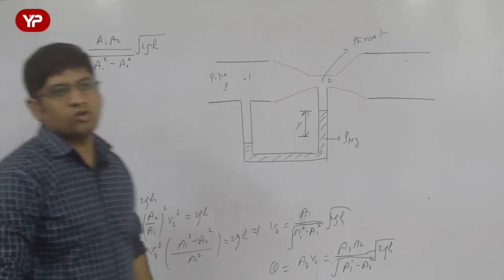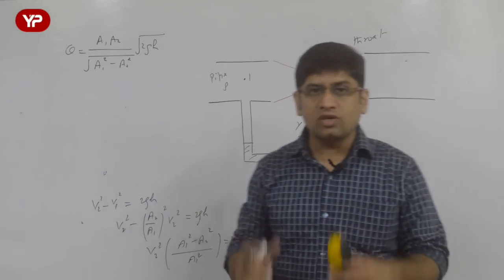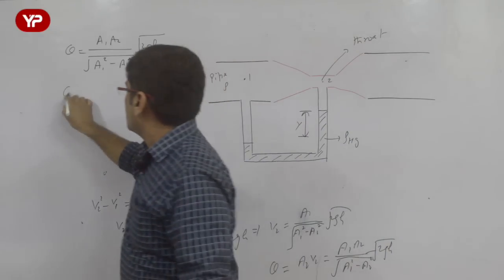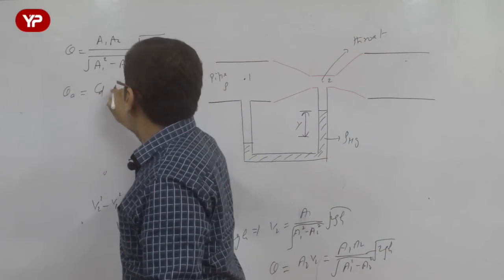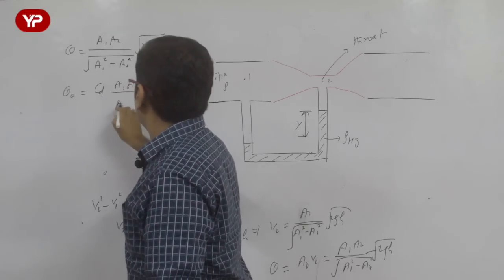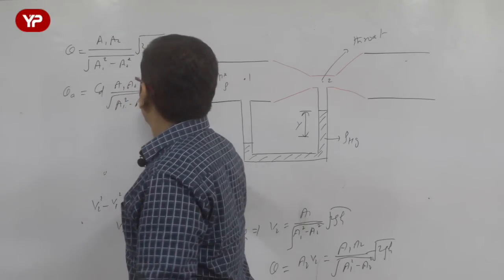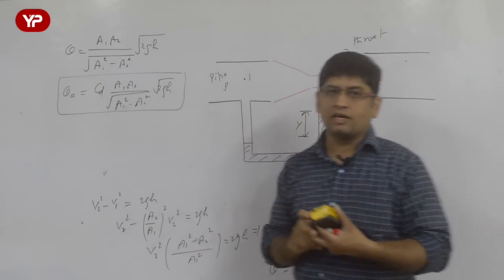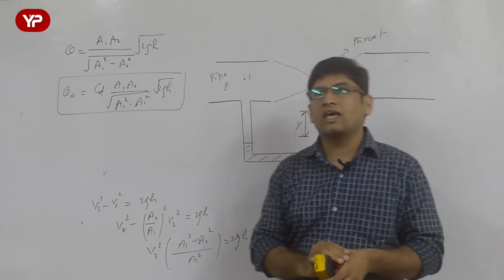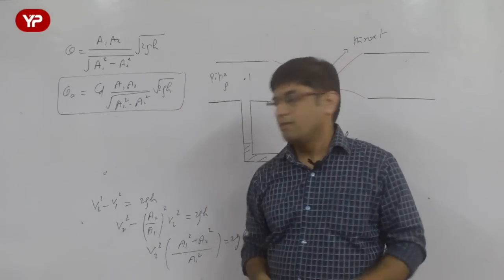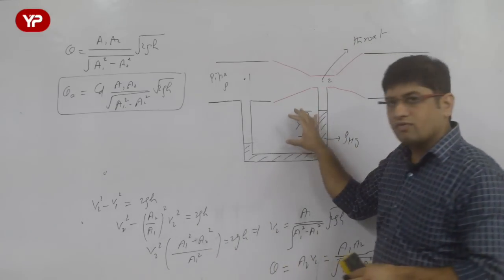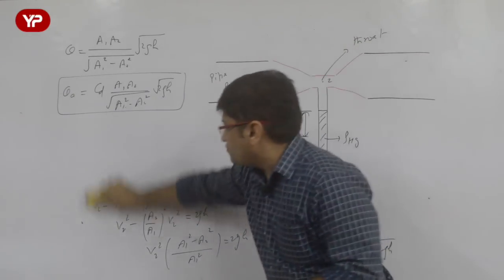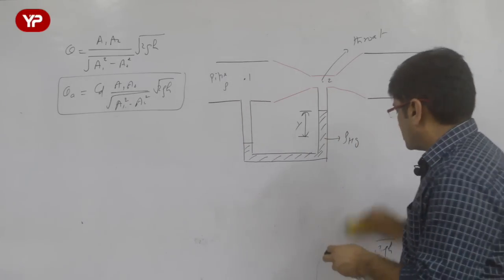That is the discharge. But you know, this is the theoretical discharge. The actual discharge is to be obtained by considering some losses because of the change in area. So actual discharge is equal to Cd A1 A2 over root of A1 square minus A2 square, into root of 2gh. This is the actual discharge through venturimeter. You need to remember this formula, and whenever A1, A2 and h are given to us, h being calculated from the limb difference, where h is the difference of pressure head, then we can calculate the value of this particular discharge through venturimeter.